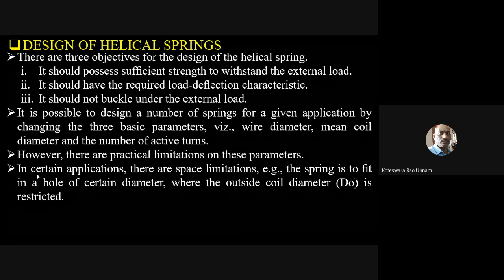That is my application. Since you need to insert the spring into the hole, you cannot take the outer diameter of the spring more than the hole diameter. Outside diameter of the spring should not be more than the hole diameter. If it is more, you cannot insert the spring into that application. So you cannot use that particular spring in the given application where you want to insert the spring into a hole.